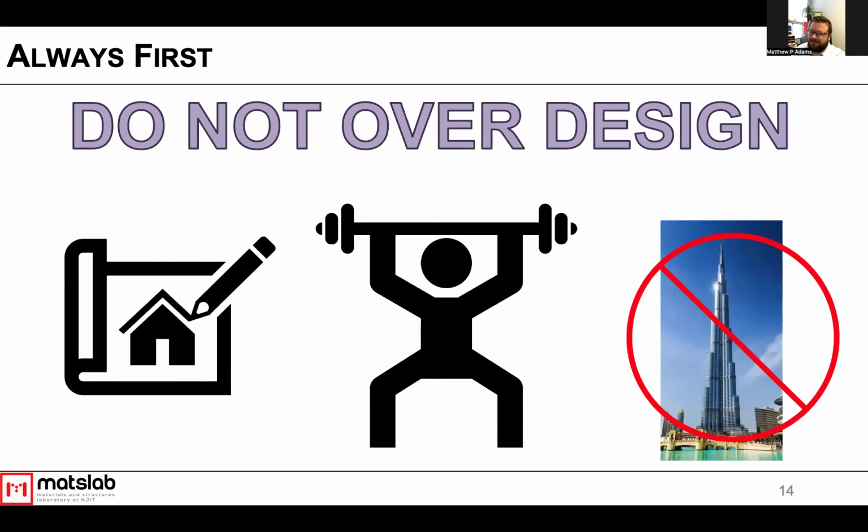And then finally, don't over design your buildings, right? Not everything we design is the Burj Khalifa. Not everything needs to be super high strength concrete. And even if you're talking about your normal strength concrete, I've seen a number of designs out there where you're ordering 25 megapascal concrete, and then on day 7, your concrete breaks are coming in at 40 or 50 megapascals.